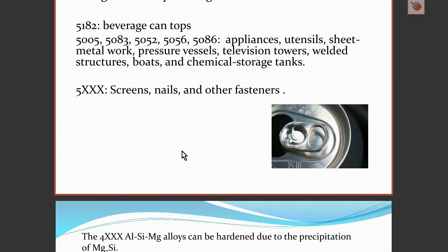And this leads to a recycling issue with aluminum, in that we have a mixture of alloys in the aluminum can, and we cannot simply just melt it down and make other cans out of it, because we have a mixture of the ideal alloying constituents.